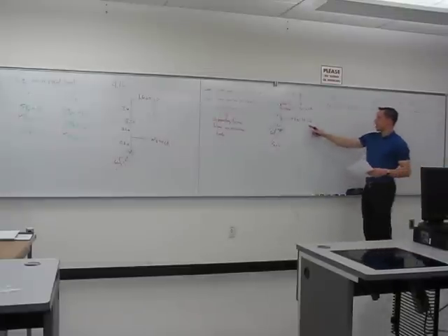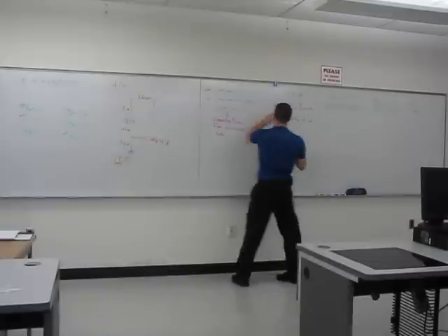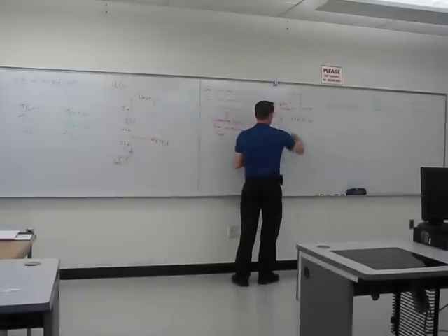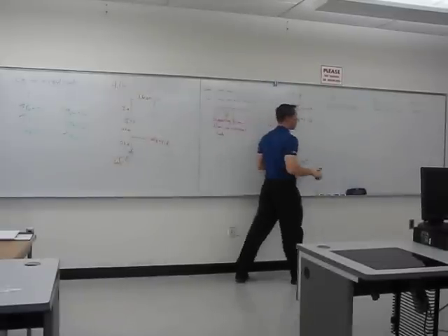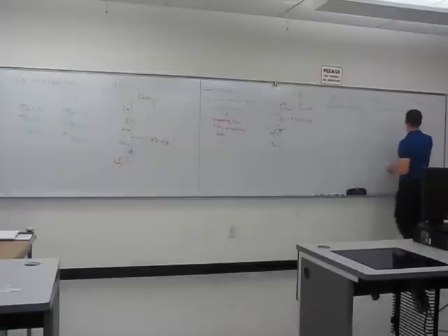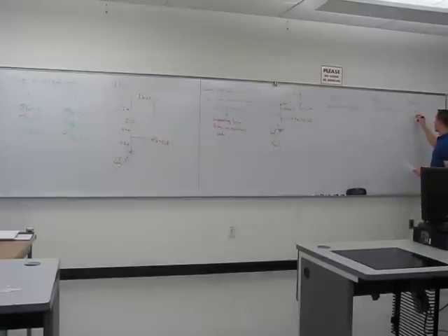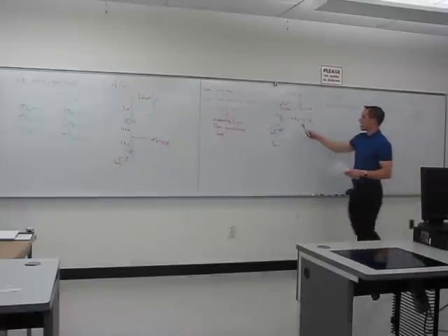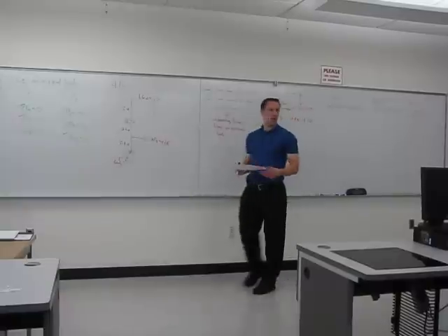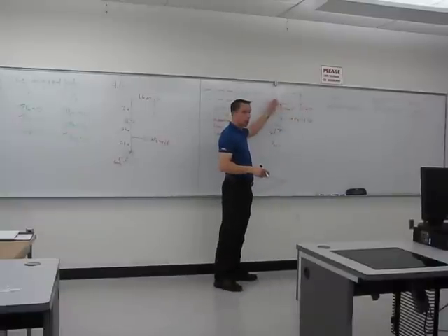The force at B, again, hold the point C fixed and push to the right. That's still going to spin you counterclockwise, so it's going to be a plus. Here we have FB times 0.8 inches. And then, like we said, Fcx, Fcy, their lines of action go through the point C, so there's no moments around the point C associated with those.